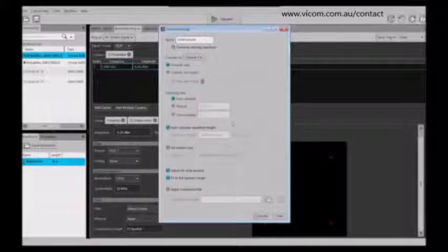And it knows which instrument you're talking to, so it will know what the characteristics are for the AWG that you're using, so that you know that you can't go past a certain frequency. Since I'm using the 2-channel box, you can see it's maxed out at 25 gigasamples. For a single channel box, it would be 50 gigasamples.